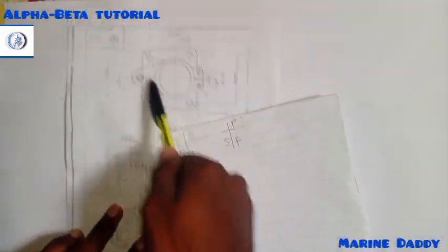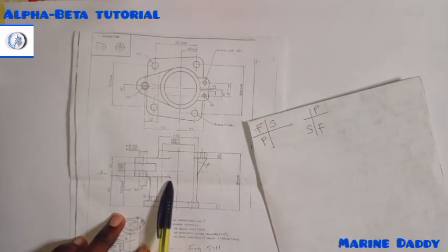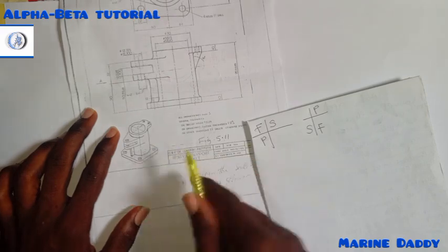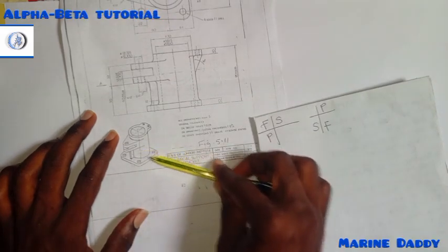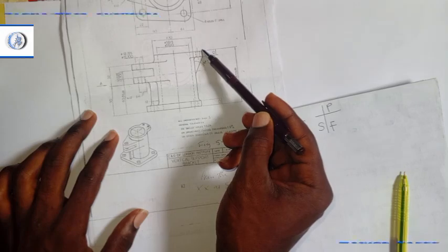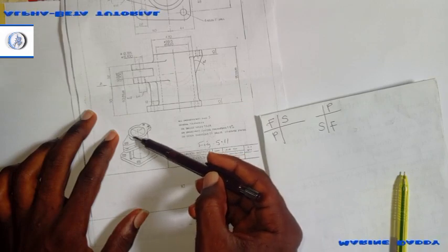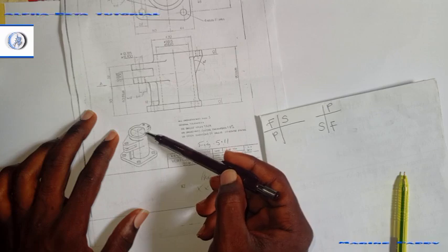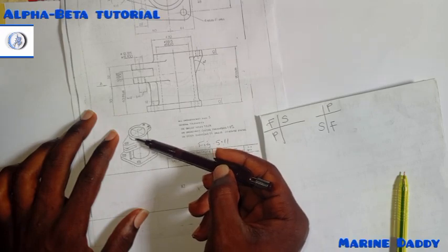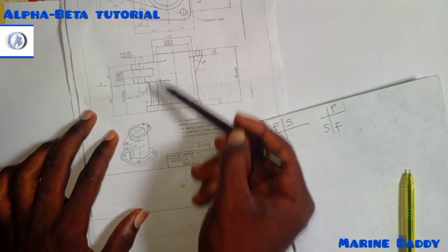I'm having the plan here. Then obviously this side is supposed to now be my front view. And how do I know? Looking at this diagram, this is the front view of the diagram when you're looking at it from this place. And what can you see? This part of the diagram that projected to the end, this hollow part, try to go and watch the video. You see how curved parts turn straight when you're looking at it in 2D, in a 2D plane. So this curve becomes a straight line when you're looking at it from this view. You understand? So that's what we are seeing here.